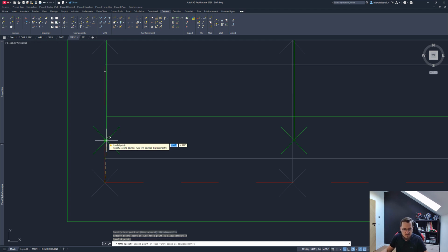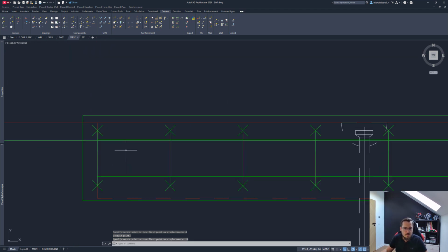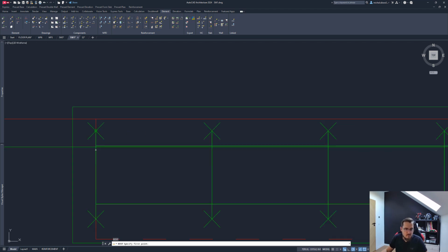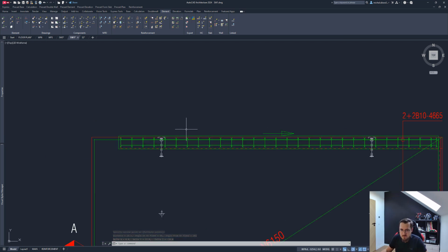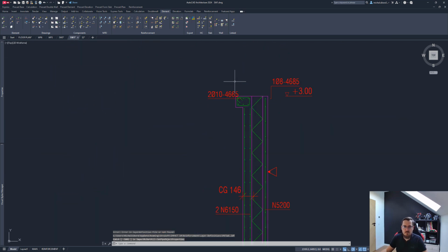Let's go displacement. Let's go 25. Okay. That's gonna be delta Z 24. Okay, should be sufficient for the demonstration. It should be perfect. And let's refresh the drawing now. What's going to happen is this is going to be a group of reinforcement. It's also going to be detailed on the side, so you will have that group nicely detailed. But while refreshing that drawing, I will also refresh the section where the reinforcement will be visible for you.